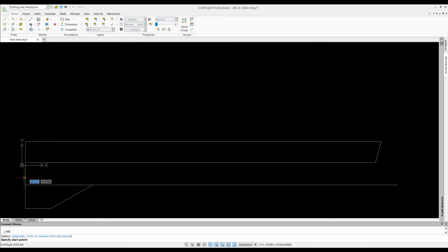So we'll go ahead and just snap there. We're going to go over 44 and a half. Oops, it's 2.5 inches from the other way, from this side. That's okay, we'll just snap it and then click again and go 2.5 down. And then we'll go over, we'll just delete that line later.